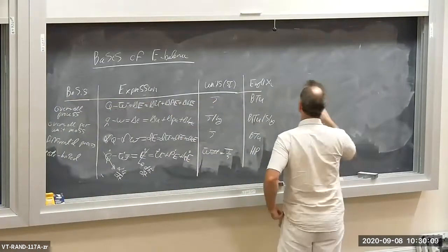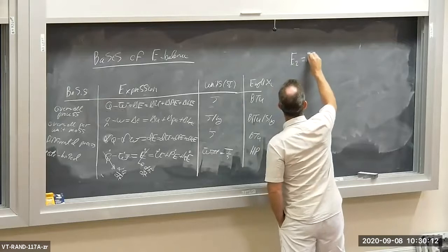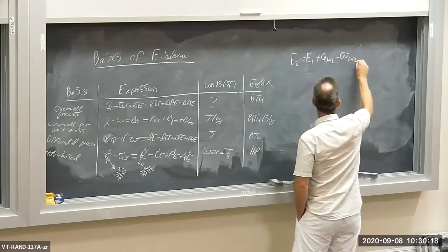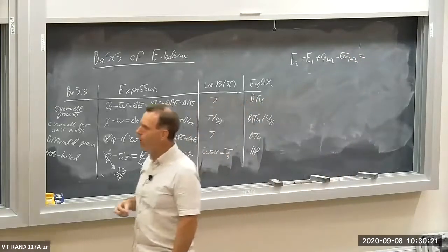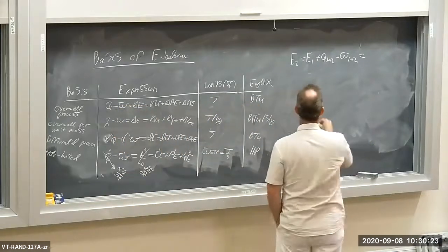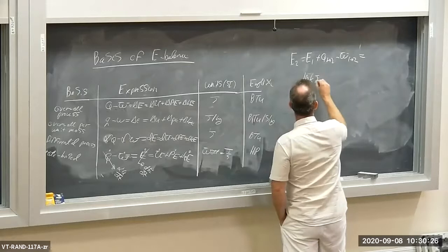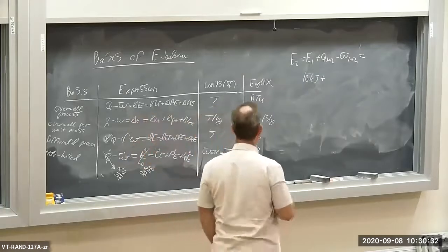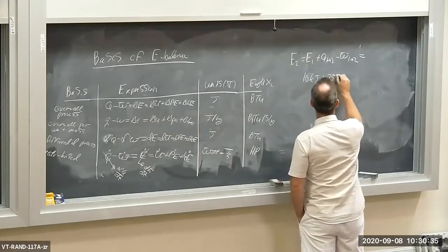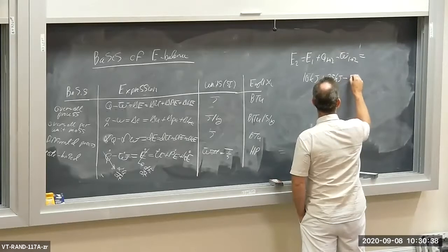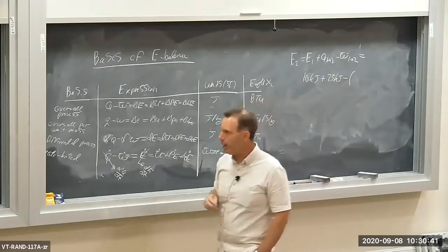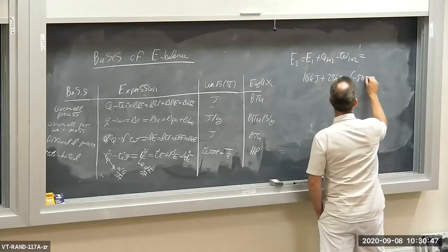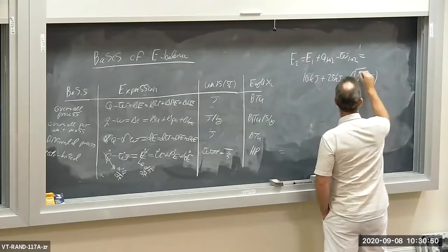So again, E2 is equal to E1 plus Q 1 to 2 minus W 1 to 2. Okay, let's plug in. E1 is 10 kilojoules. The heat added is 25 kilojoules. And then I have minus, and I need to put a minus 500 joules there. Now, why is the minus sign here?